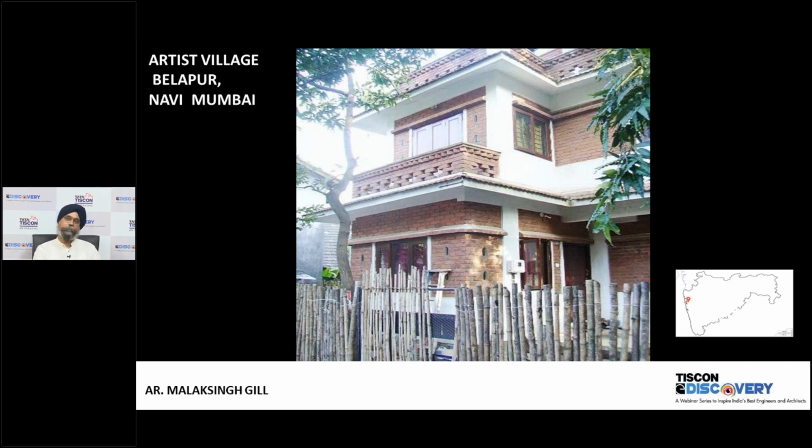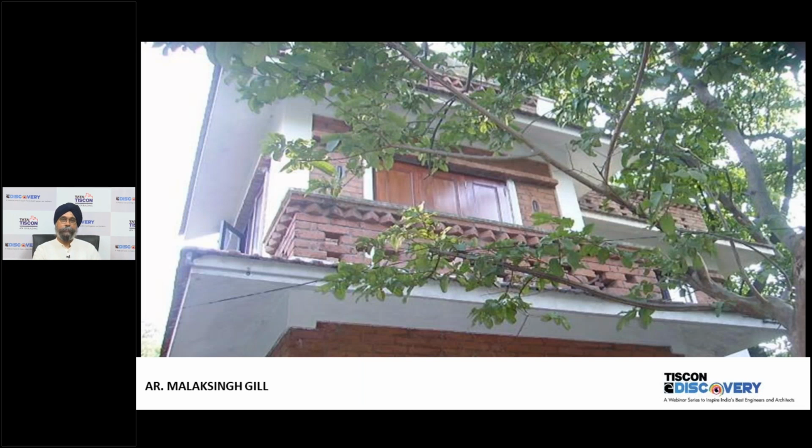Another interesting thing we did here is, of course, with the help of the structural engineer, Mr. Suhas Chande, we kept the beams only 6 inches thick, because the walls are only 4.5 inches thick. So why have the beams 9 inches? So we saved on a lot of concrete and steel like that for a lightweight building, and the slab, like the earlier projects, is also a filler slab. That's the same project.